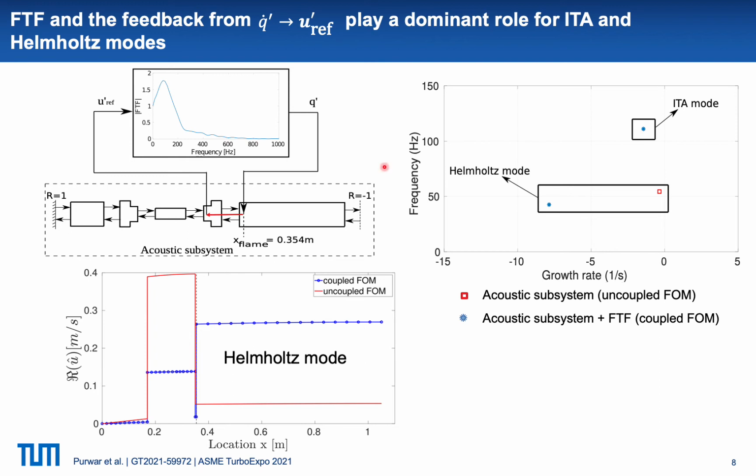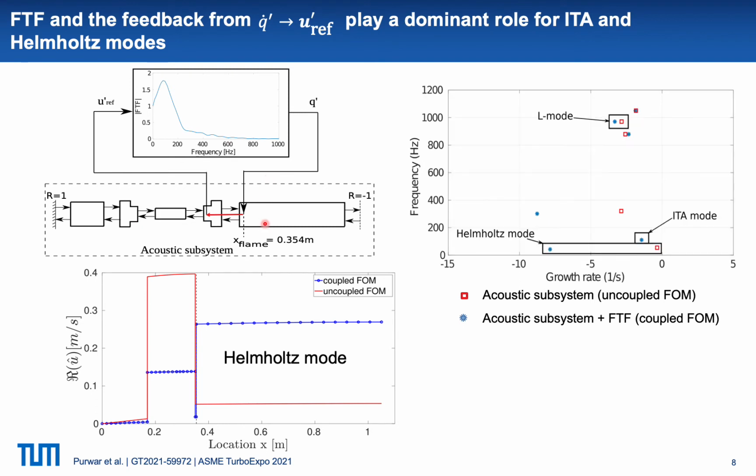To validate this hypothesis, we perform model order reduction on the acoustic subsystem with three techniques and then couple it with the flame transfer function and investigate whether the respective reduced thermoacoustic systems reproduce all of these modes accurately or not. We will use these three marked modes to compare the performance of model order reduction techniques.